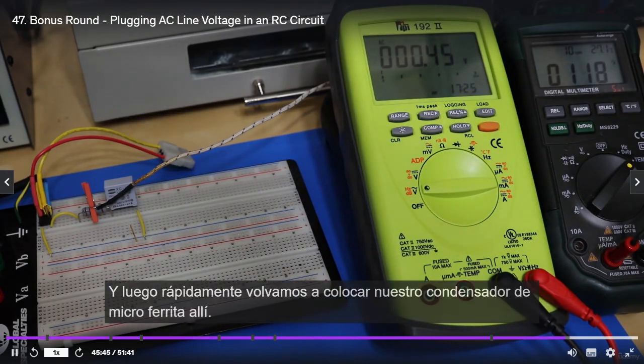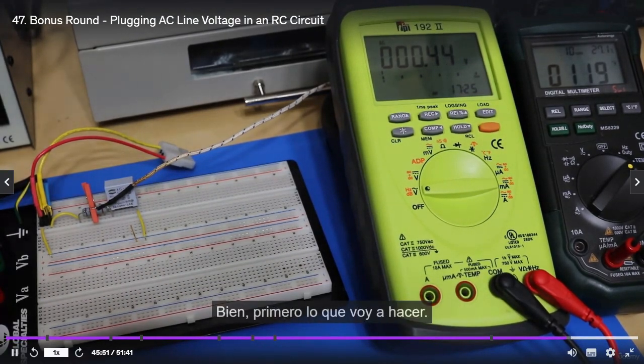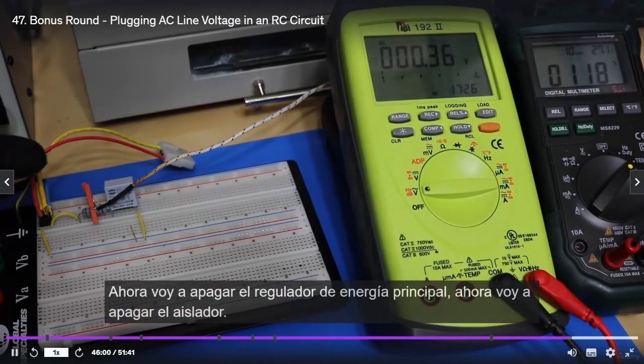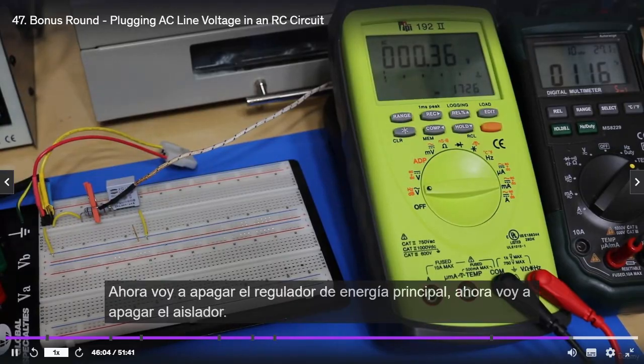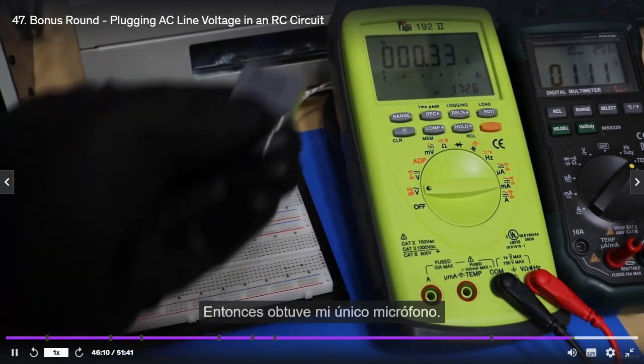All right, and then quickly, let's put our 1 microfarad capacitor back in there. Okay, let's do it. So first what I'm going to do, I'm going to reverse the variac back out slowly. So I'm backing it out down to 0. Did it. Now I'm going to turn off the main power regulator. Did it. Now I'm going to turn off the isolator. Did it. Okay, now let's get our 1 microfarad. Let's put that in there.